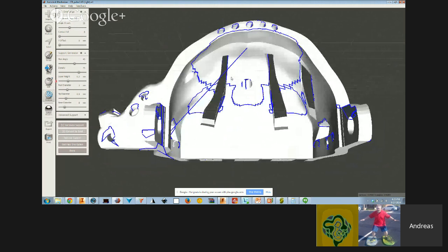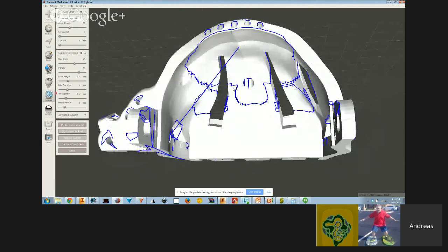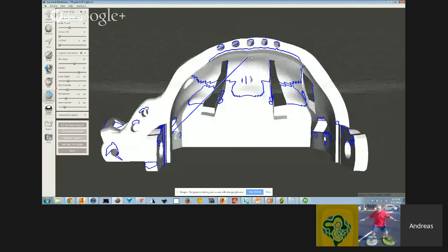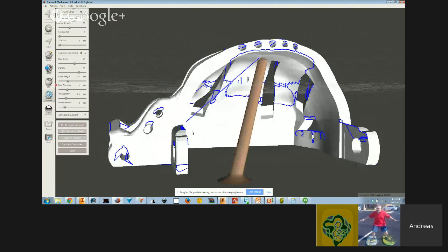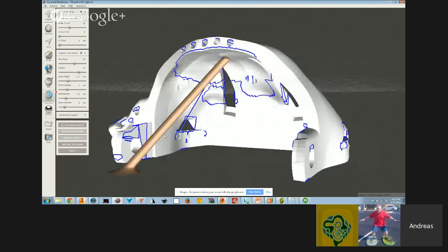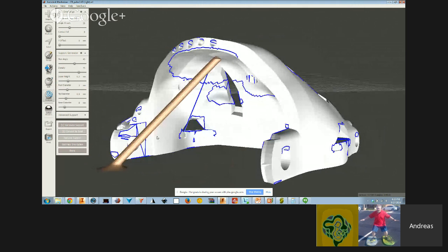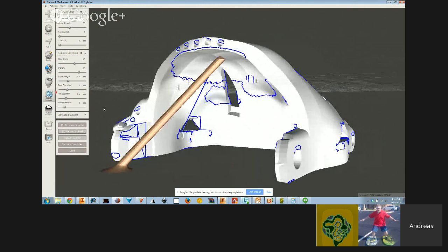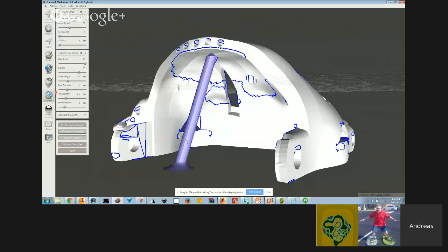So let's just focus on this area up here in the upper dome. If I just left-click anywhere there, it adds a strut there. Okay, and you can see it's kind of angling out. If I don't want that to happen, this max angle setting will adjust that. So let's say, just for seeing it, bump it up to 70, and I'll Control-click on this one because I don't like it. And then I'll click there again, and now it's at much less of an angle.